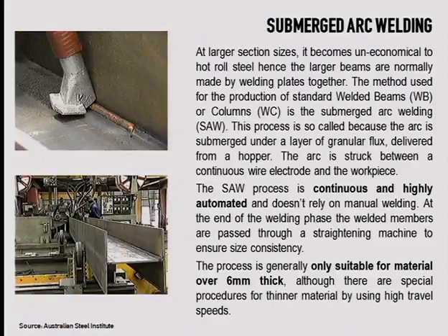Look at this one. Look at this profile here. These are very wide flange beams. So look at this. There are 3 thin sheets which are connected together by means of welding. So that's the way to realize that. There is no hot rolling process to do that. You could do it, but it would be incredibly expensive.